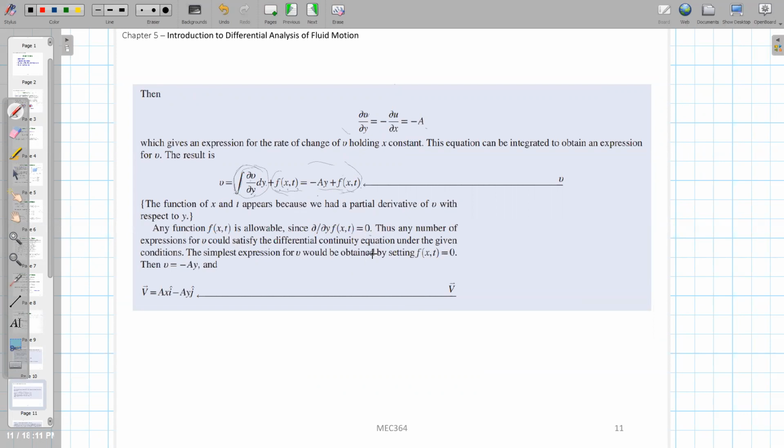And this shows you how to use mass conservation to get the detailed velocity field inside this fluid, right? And for example, if we know the boundary condition, we can find what this f value will be. Now we know the exact flow velocity field inside this whole fluid domain. This is the thing that you won't be able to get from the integral form of the equation, right? It won't give you the specific u and v velocity inside.